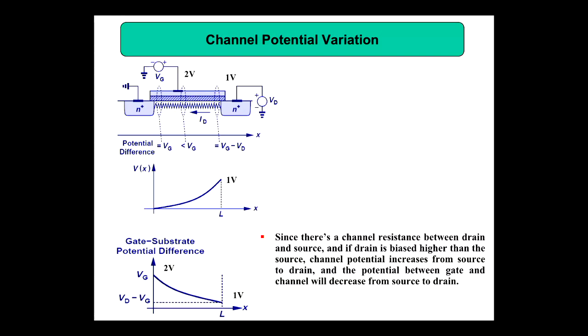Yeah, so that is Vg minus Vd. So that is correct, there was a mistake. That's Vg minus Vd. But one thing is there, it is better to take the modulus, because sometimes you may connect Vd to a higher value. Now I have connected 1 volt, but when you are operating in the saturation region, your Vd will usually be a larger value and you may get a negative. So Vg minus Vd is correct here, but we will put maybe a modulus.